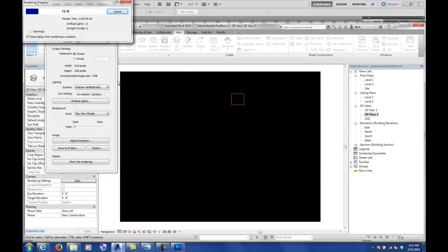Then we're going to send the same thing up to the cloud because I want to show you something, the error that you will probably encounter many times unless you are aware of this as an issue. The issue is, when you send information to the cloud, it actually uses the materials and everything that came with Revit on their server up there, wherever that might be located.